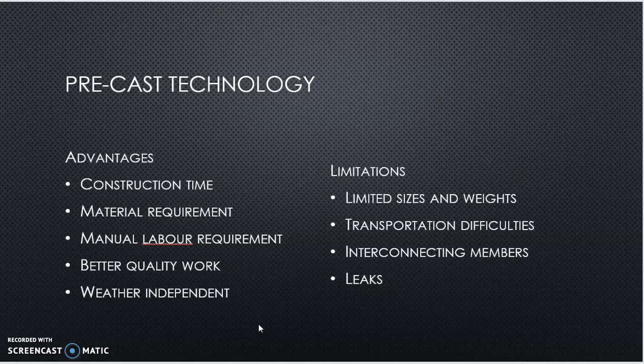So similarly in this, you will have to choose the element which is manufactured or which is ready at the yard, because you're going to repeat the same formwork again and again. What is formwork? I've been using this word very often. I hope you all are aware of what is formwork. Formwork is basically, when you pour concrete, it will take the shape of the mold in which you're pouring it. So that mold, which is usually made up of plywood or timber, is called formwork.